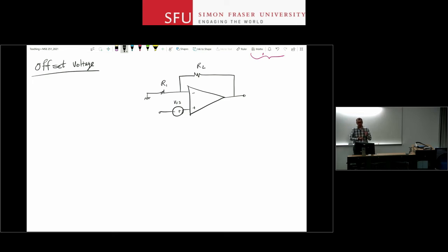In a second approach, they actually have circuitry inside the op-amp that actively monitors the offset voltage at the output and plays with the biasing, as the user did in the manual case, to compensate for those changes and ensure the output offset voltage is 0. So the offset voltage is there, you have to deal with it, and I think your best bet in most situations to get rid of it or reduce its effect on your circuit performance is to just choose a better op-amp. You have tons of options available to you nowadays.